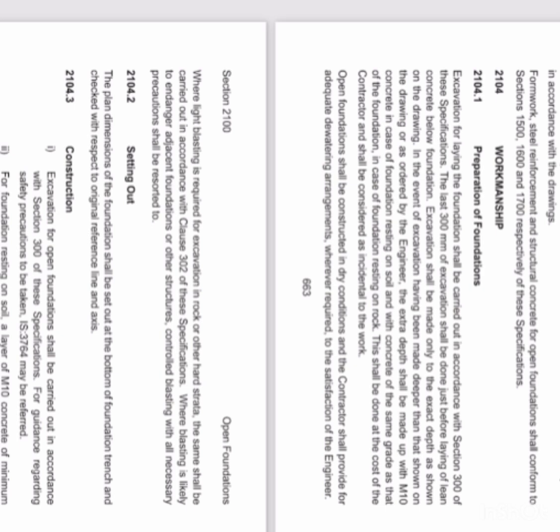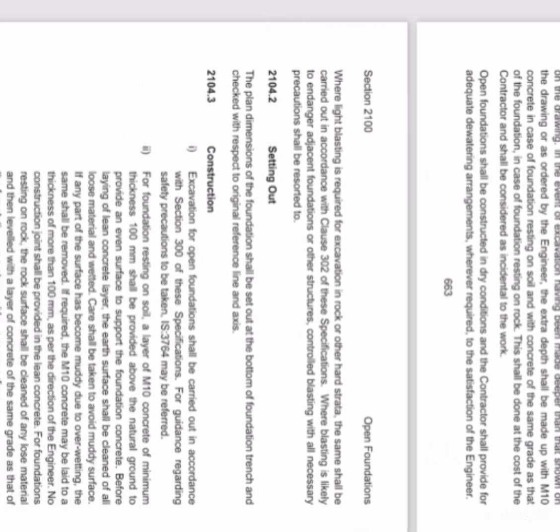Where blasting is likely to endanger adjacent foundations or other structures, controlled blasting with all necessary precautions shall be resorted to.